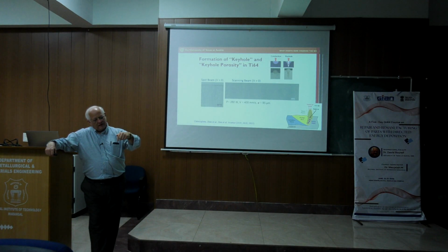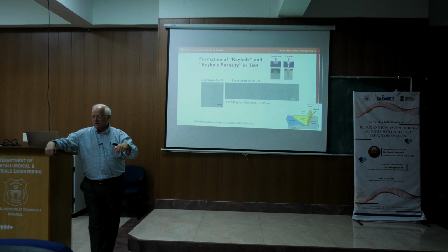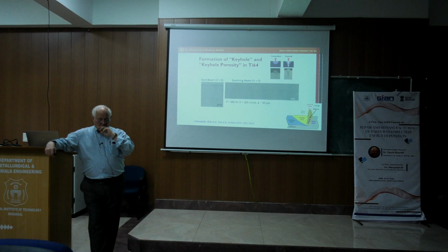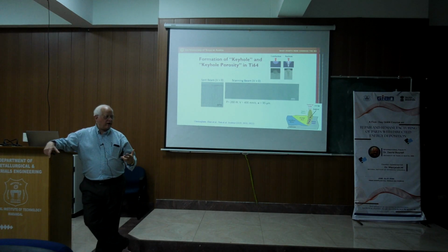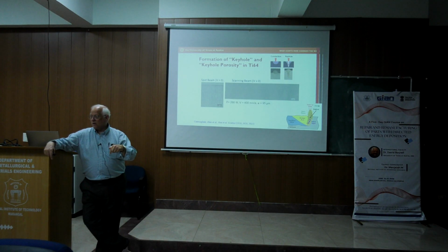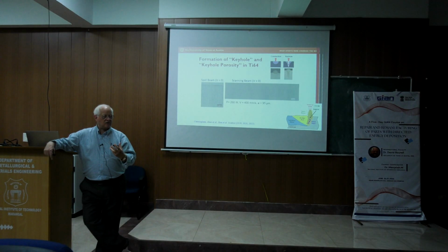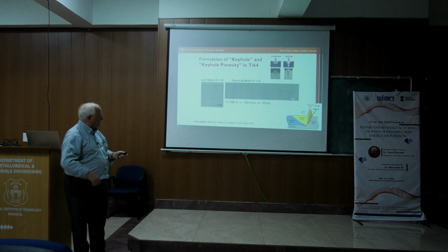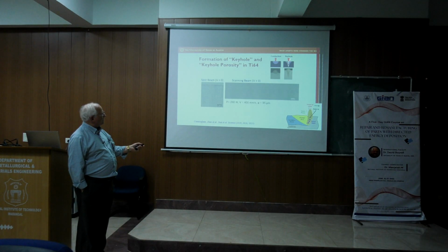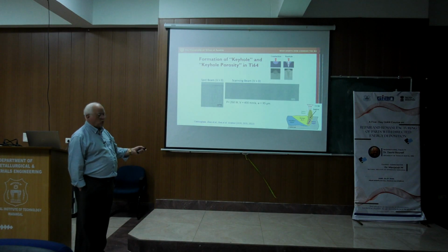The phenomenon is that the laser beam strikes the surface of a material, and if the beam is sufficiently energetic, we melt the metal. But with keyholing, the power is so high that the liquid is actually vaporized into a sort of plasma, and the effect is what we call a keyhole. It's a very deep penetration.